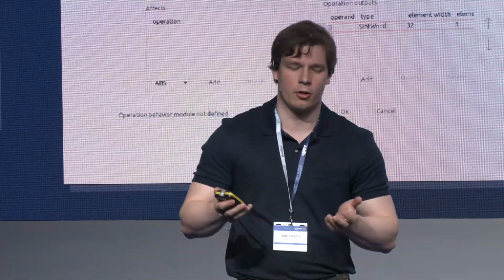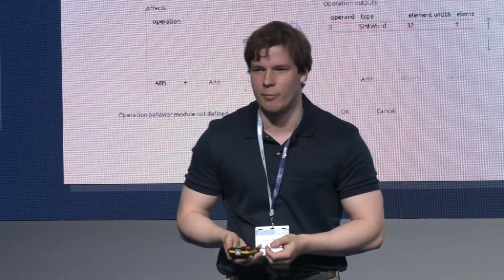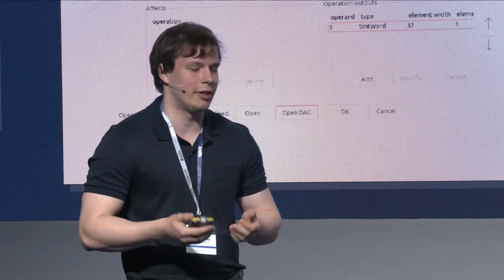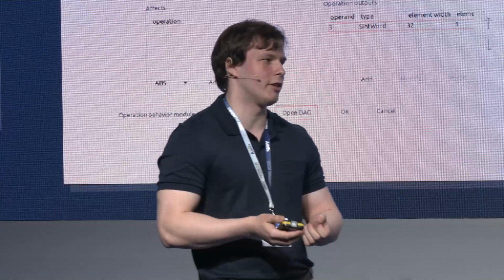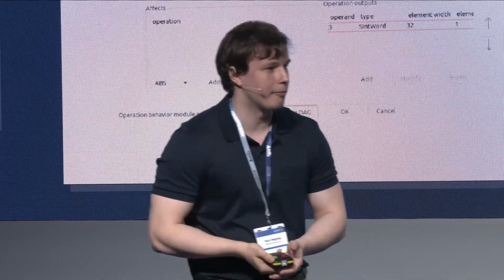You're now doing RISC-V. Previously, you did transport-triggered architectures, TTAs. They are very, very different. Which do you find better? What do you get the best results with? I have no favorites. RISC-V is obviously better for general-purpose computing that has branching code, for example. And these TTAs are usually used for DSP applications, for example, where there's a high amount of static instruction-level parallelism. So in those scenarios, TTAs can really shine, but they're not as efficient in general-purpose computing as RISC-V.